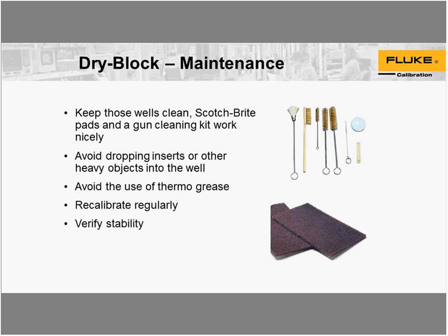Usually, I would recommend a 400 to 600 grit sandpaper to clean them up. But typically, a gun cleaning kit with some of those brass brushes works well to keep the wells very, very clean. One tip: don't use thermal grease in a well. I've seen that happen a few times.